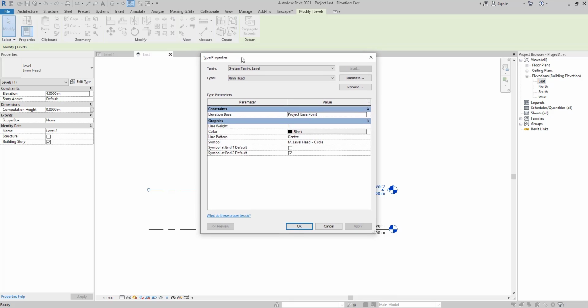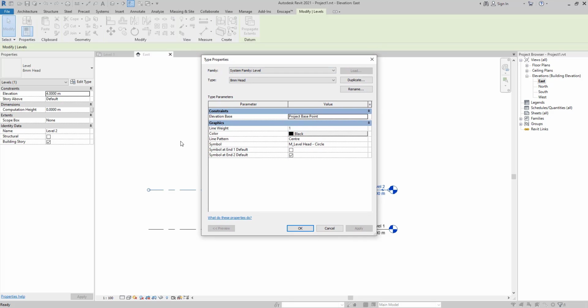Here we are going to have a very important note. Anytime you want to create a new default for your design, a new graphic or new setting for anything, like you would like to create, for example, a wall with details, or you want to change the window height or dimensions of something, the color of something, the material of something, any type of edit you would like to do on one default file, or you download the family and you would like to change the default of that family, you should duplicate your family.